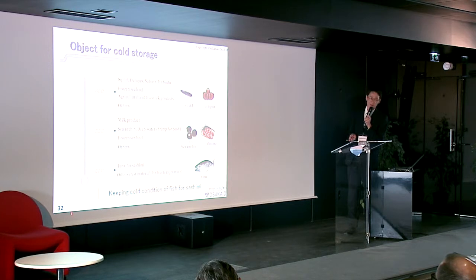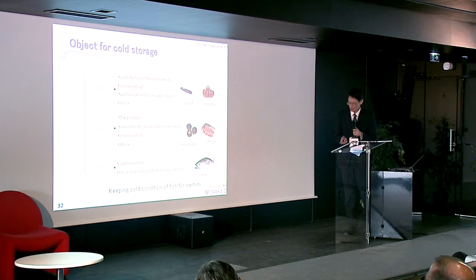In Japan, if we apply minus 40 degrees C, it's better to use an electric refrigerator because of the high facility cost of energy utilization. But we can apply cold energy utilization for minus 60 degrees C, because an electric refrigerator is very expensive in this temperature region.